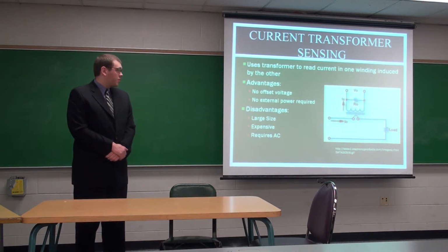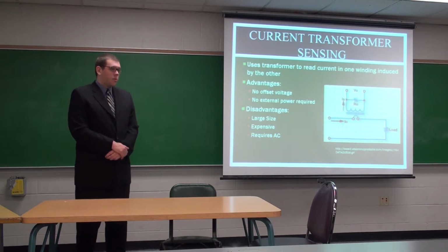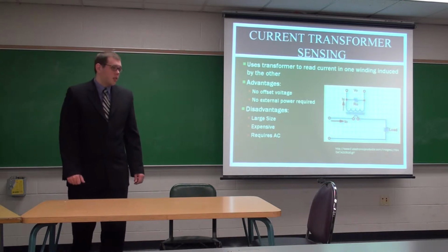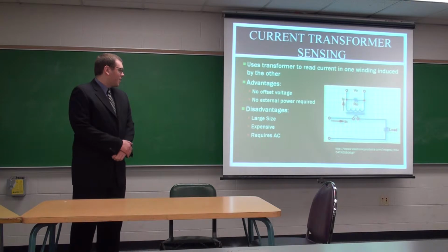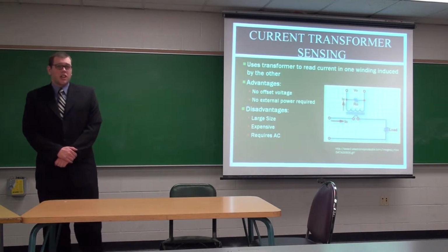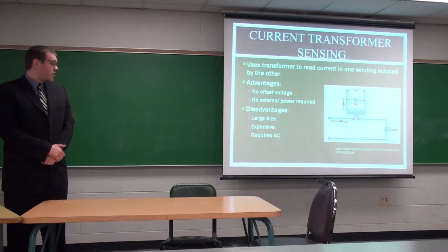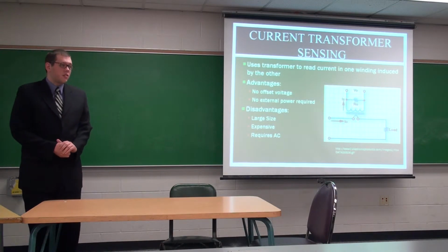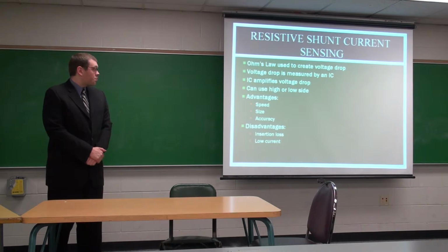The advantages of this is, again, there's no offset voltage, and because it is a transformer, there is no external power required. And again, with disadvantages, because you're using inductors, it is a large size. It has a larger size than most other things. It's expensive, and it requires AC current to actually sense the current going through.